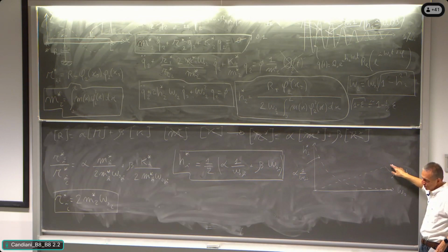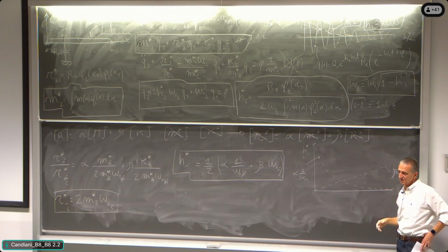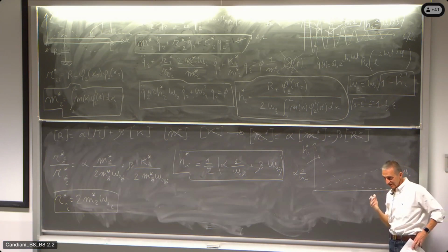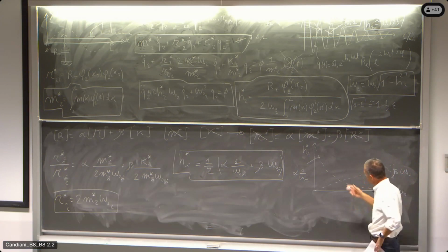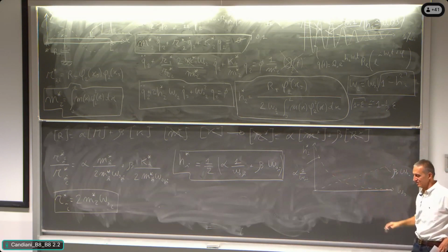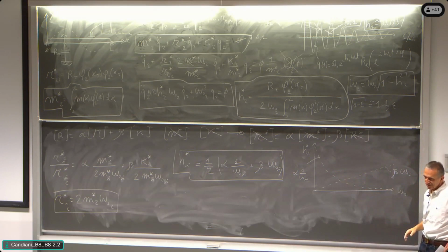And so a modeling like that, for sure, is saying that the higher modes somehow have more damping than the lower modes. But at the same time, it is saying that it is not mandatory that the lowest modes have the lowest damping.